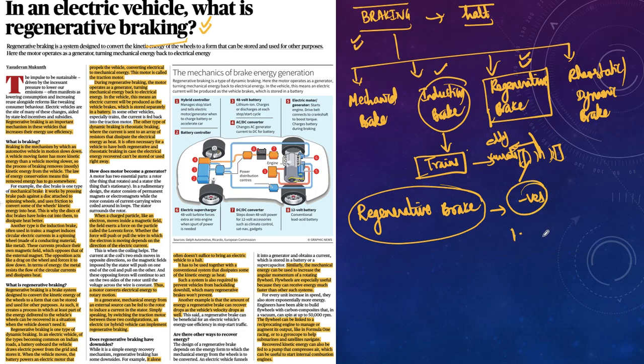One of the biggest problems is we cannot make the vehicle come to a stop all of a sudden in case of regenerative braking system, or in busy traffic areas inside the city we cannot use it. That is why in electrical vehicles we will be having a hybrid brake, that is regenerative brake we will use in less traffic areas, and in busy traffic areas, or in an emergency when you wanted to stop all of a sudden, we can go for conventional braking system. So that is one negative in case of regenerative braking. So you are still dependent on conventional brake in some of the places.